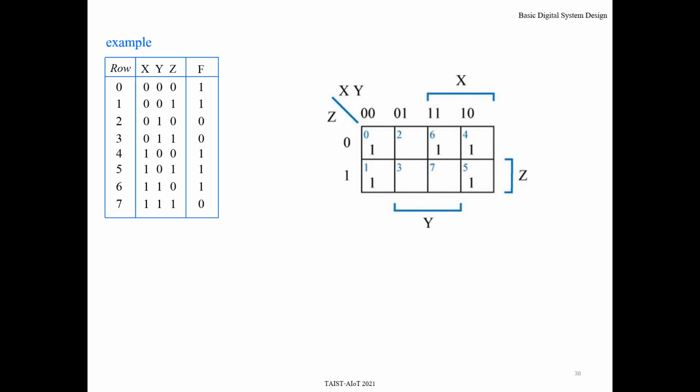Another example for this one, when you write it out, the K-map will give something like this. Now, to obtain the function by using sum of product, that means we must select all of the logic 1 output. Anyway, to minimize, you must select a bigger rectangular group of the one cells. Namely, you select this one, it's okay, but not optimal.